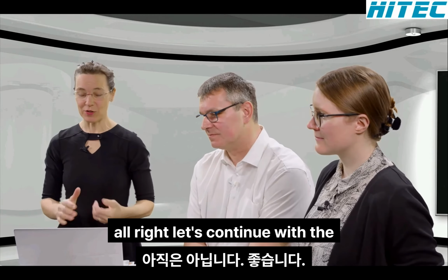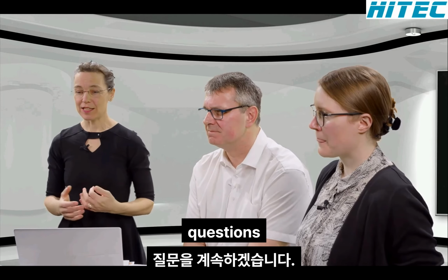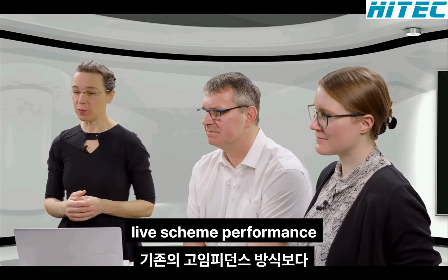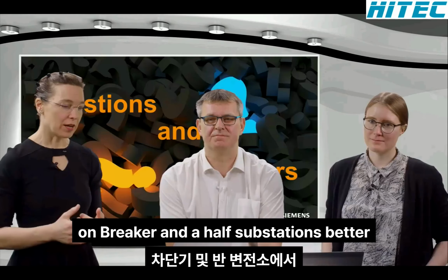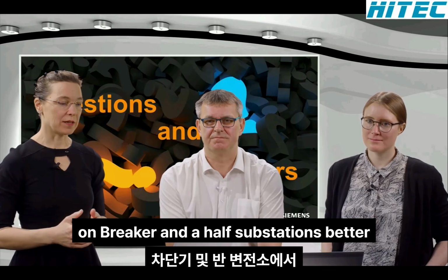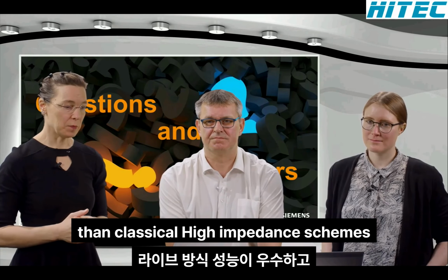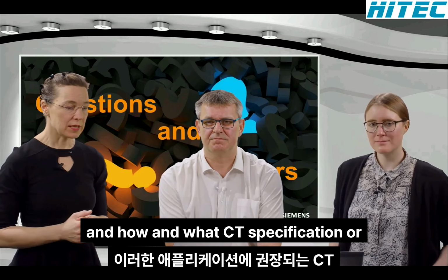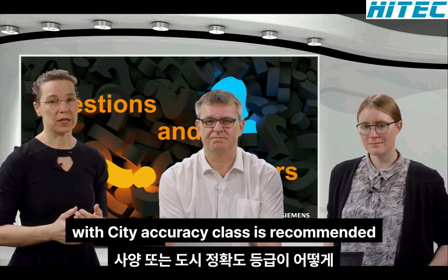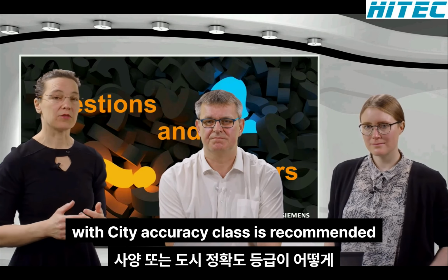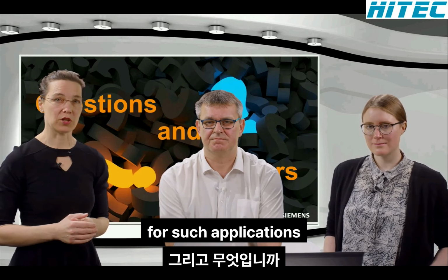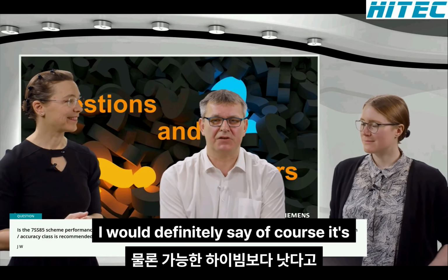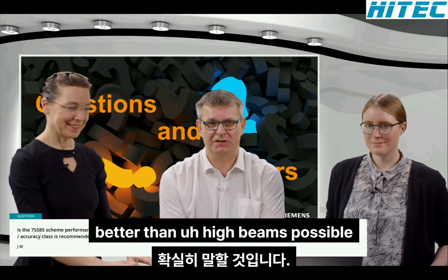All right, let's continue with the questions. Is the 7SS85 scheme performance on breaker-and-a-half substations better than classical high impedance schemes, and how? And what CT specification or accuracy class is recommended for such applications? Yes, I would definitely say it's better than high impedance busbar protection.